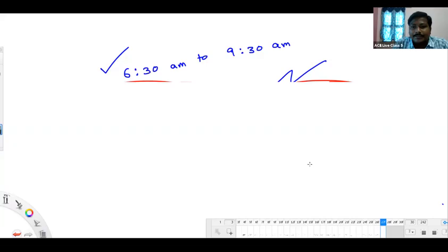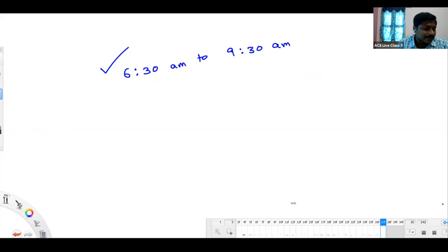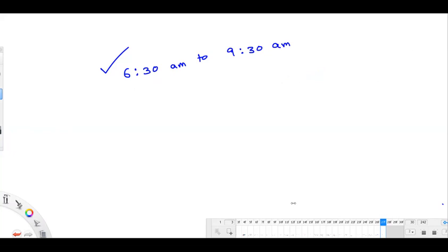Akshay. Good morning, sir. Am I audible? Yeah, tell me, Akshay. Sir, one doubt I had was direct lightning over voltage. When we say that, it means that the lightning directly strikes the power lines, right? Yes, correct. And that is avoided using the earth wire or ground wire. Yeah, correct.